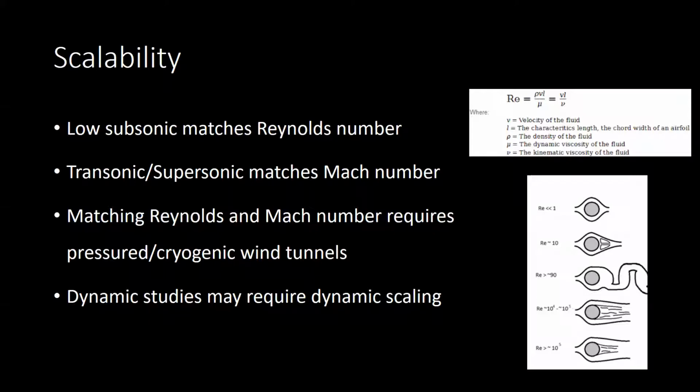And then I also like to point out that you can perform dynamic studies as well, such as a rotating or moving body, but you might need to have some dynamic scaling involved as well, such as scaling properties like moment of inertia, your center of mass, or even sometimes, depending on the experiment, you might want to scale your material properties.